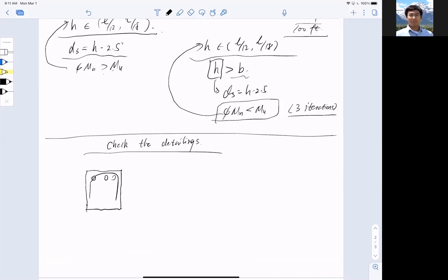If I were a construction manager, I look at this, I will feel very concerned because I don't have anything to go on. What is the spacing between bars? What is the concrete cover? And even what is the minimum beam width? Does it work at all? And at minimum, you have the ACI table or textbook Table A5 with you. You can simply check whether your beam width satisfies that requirement or not. Even if you just did that, I give you the full score. At least you thought about it.